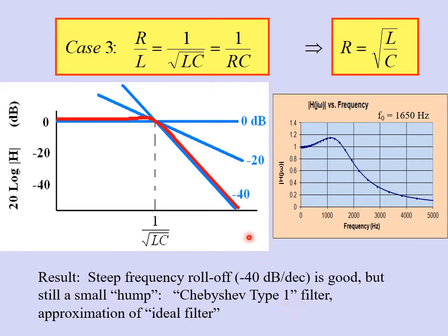And there's always trade-offs in filter design. So this one has a really nice sharp slope right here after the corner, and the only downside is there's just this slight little hump here at the corner, but for an audio filter that is usually not even detectable, something this small. So this would be a good design to use.